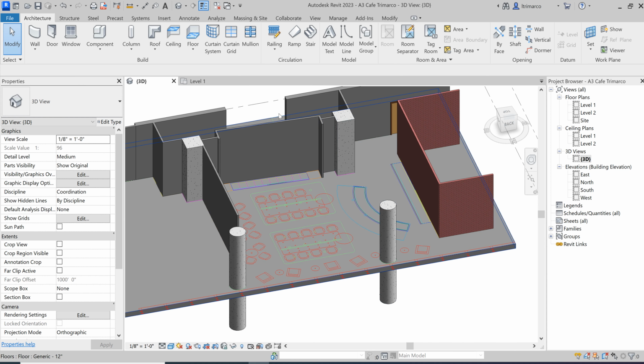First off, where I get some of those families is obviously through inserting a family in Revit. A quick way is obviously just going to the Insert tab at the top of your screen, and to our right, again at the top of the interface, is a button called Load Family. If you select it, you will open up the English Imperial Library, and this is all the categories that we have in Revit. And if you scroll, oh gosh, it's right at the top. It's the fourth folder from the top.